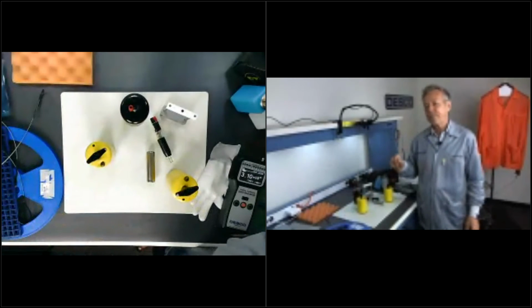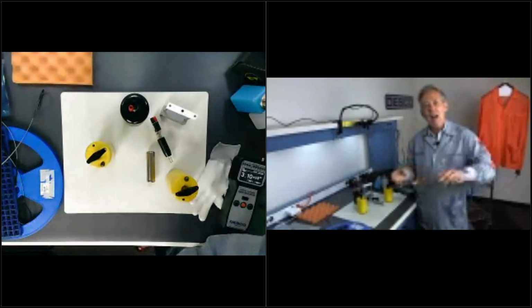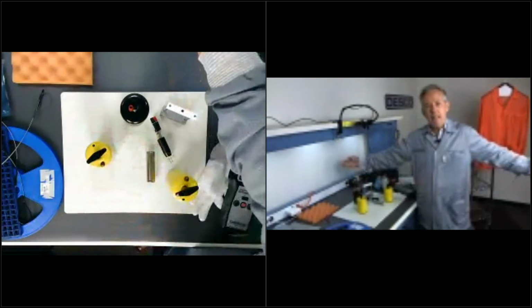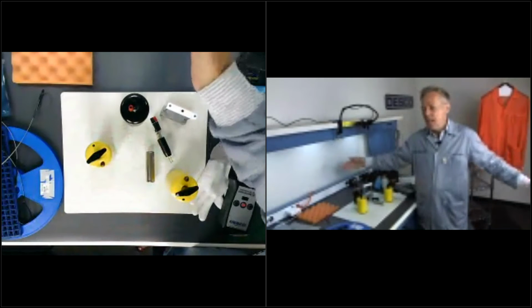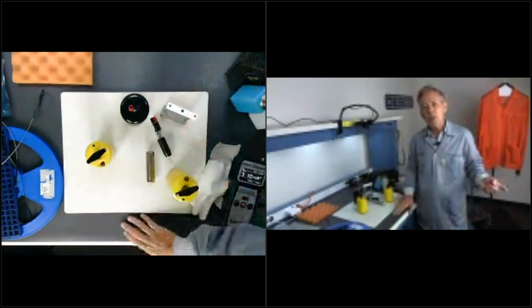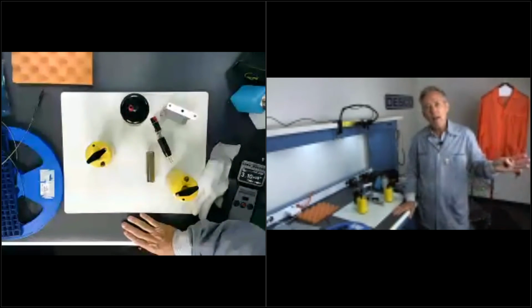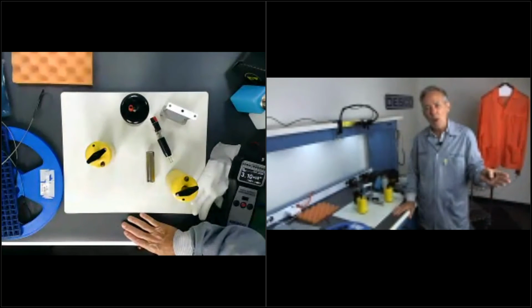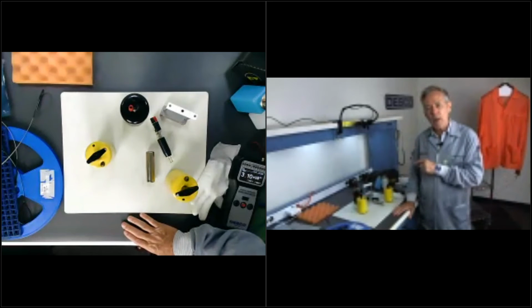Now the challenge is, if I have a ground rod, how can I check multiple points? Because my test leads are only 6 feet long, for instance. So that's really the advantage of using my AC ground, because I can pick up a ground anywhere. I could check ground on 20 points on my floor if I wanted to. That's one of the important reasons for using the AC ground, because it makes it so much more convenient.